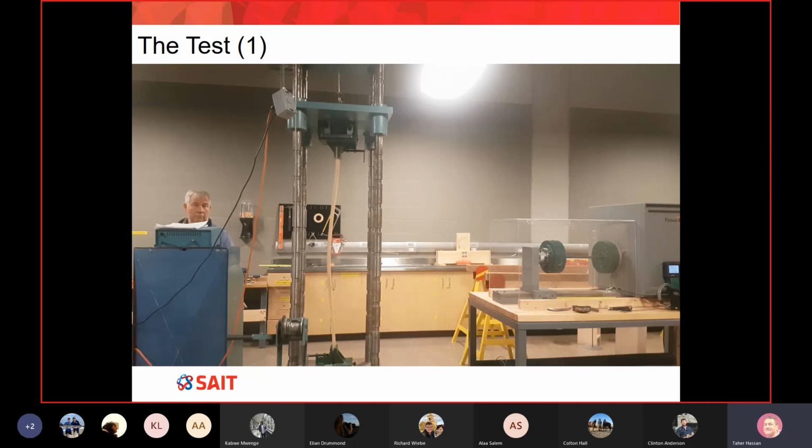Okay, so our first video is over. Before I show you the next video, please take note of what is happening here where the column is connected to the machine. This bracket ensured that at the beginning there is a straight line, so there is no rotation. And later on, I'm hoping you are able to see the curve. The curve will not start from the very beginning, it will start somewhere here and end somewhere here, because we have this end condition where it's fixing. This bracket or jig is fixing. It restrains, it prevents rotation at the beginning.